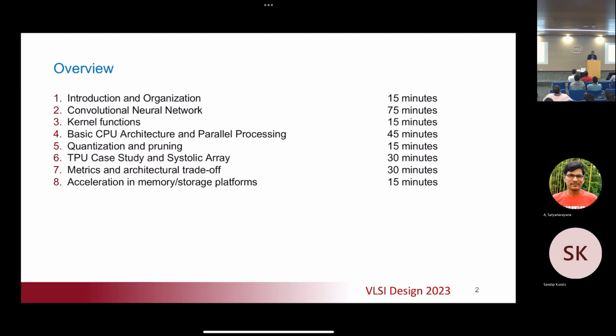You don't need to speed up that 10% because the cost may not be justified in terms of power and transistor count. That's why we only accelerate the kernel functions, the functions that you invoke repeatedly and where acceleration is going to give you benefit at a reasonable cost.